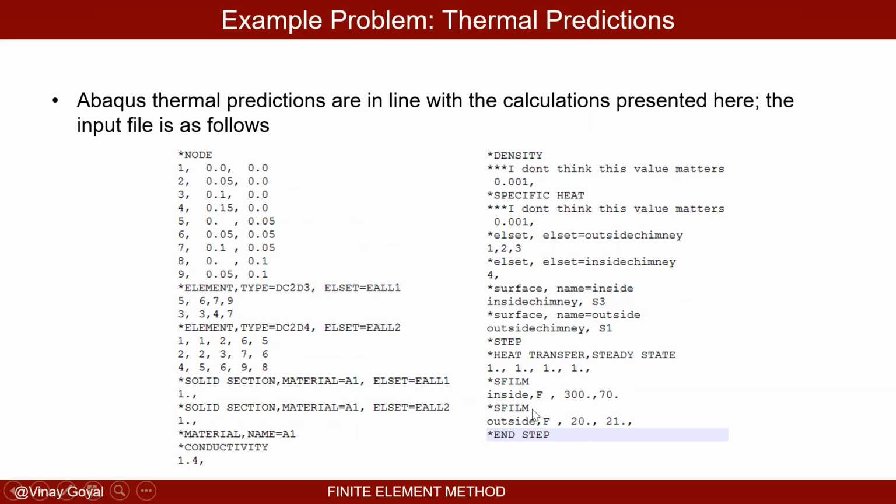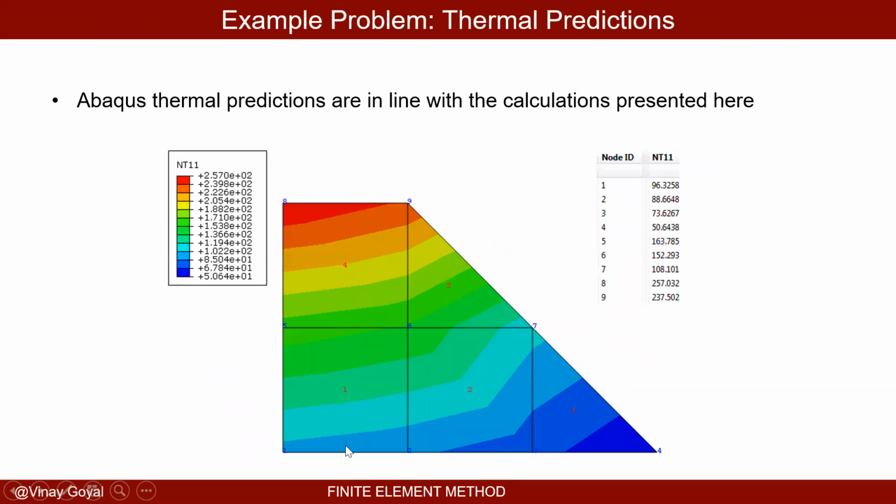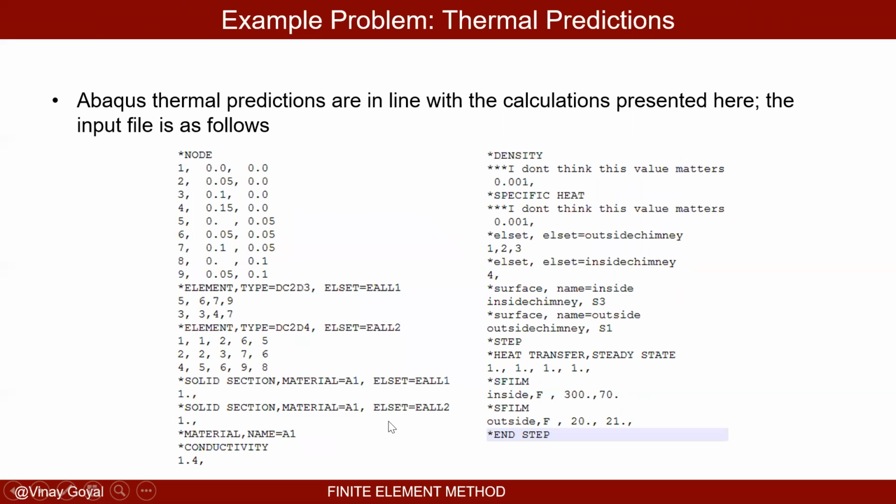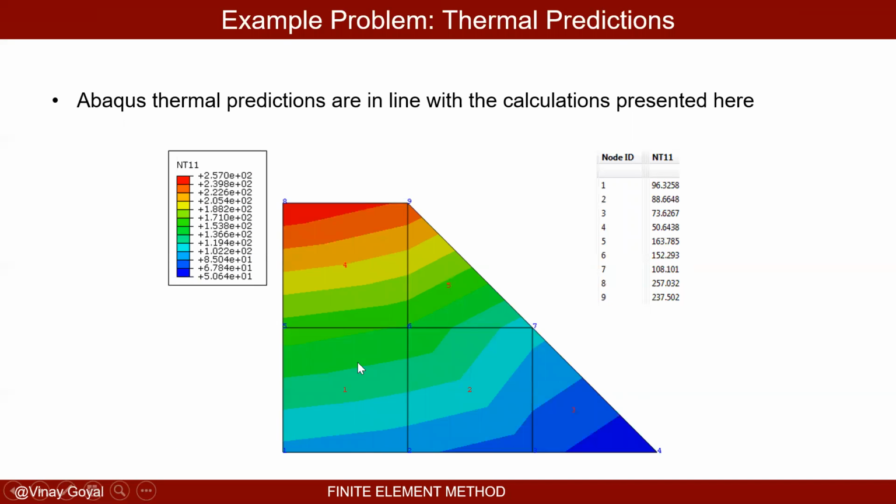And you're telling it to apply to the inside and outside, which are defined in these surfaces. Surface here and surface there. And that's defining the side of that element. An element has 4 sides if it's quadrilateral, 1, 2, 3, 4. In Abaqus, you're specifying the side that we're discussing for which heat is applied. That's pretty much it, and that'll produce these results.